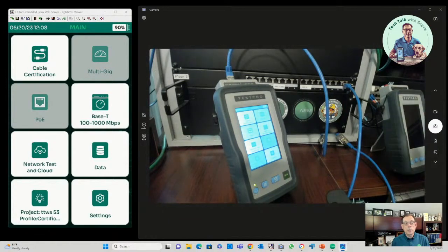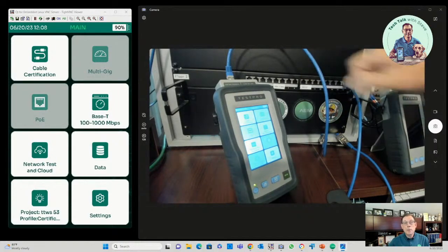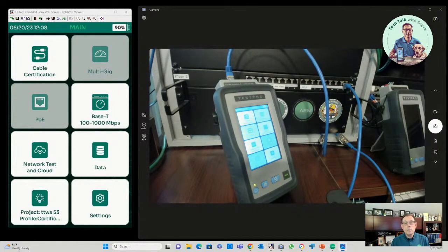So the cable has to be terminated with shielded connectors first off. At the patch panel end, that shield is part of the grounding system in the patch panel, and that panel gets bonded to the grounding system. So at that end, it is grounded. It's bonded to the grounding system.